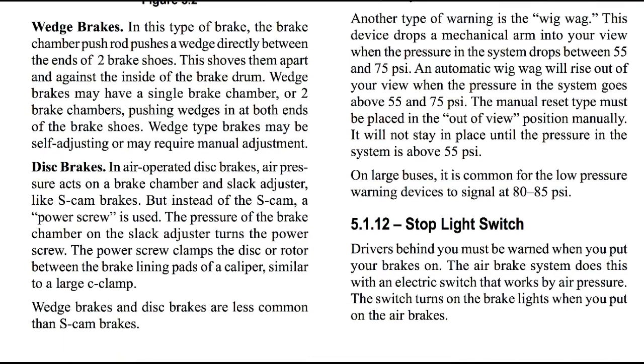The stoplight switch. Drivers behind you must be warned when you put on your brakes. The air brake system does this with an electronic switch that works by air pressure. The switch turns on the brake lights when you put on the air brakes.